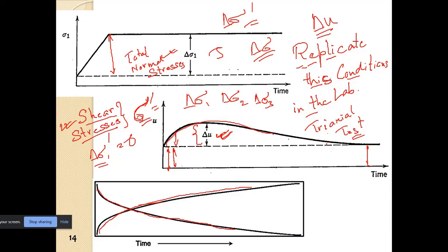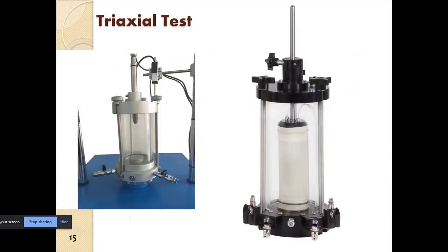So what is basically the triaxial test? First of all, we have the triaxial cell, and it is basically a cylindrical encasement. Inside it is hollow, so this is a hollow cylinder, and inside we have a pedestal here. On this pedestal we can put the soil sample.